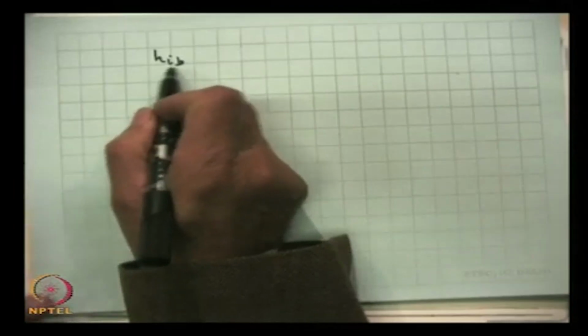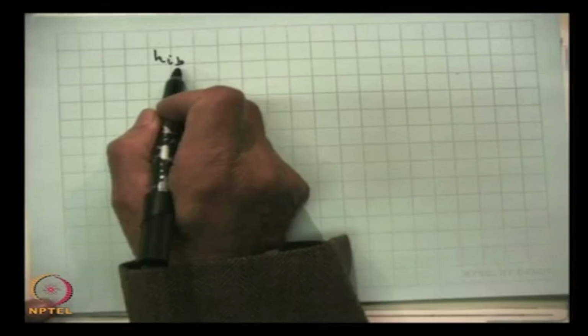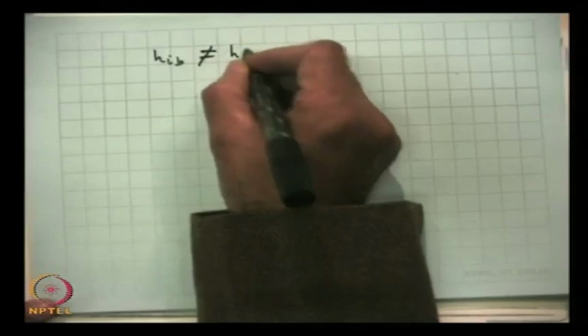This is being said repeatedly that h equations are invariant, whatever expressions we will be deriving, for example, for voltage gain, current gain, input impedance and output impedance, these equations we will be deriving in general. And then we will see that hib, this represents the input impedance in the case of a common base, and this is certainly not equal to hie.